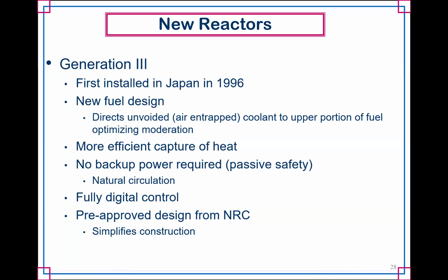So you can just rely on natural circulation, just the way things are designed naturally, where you heat things up, you have less density, they float up above, and then the cool stuff is more dense, and it goes to the bottom, and that's how you can get some cooling.